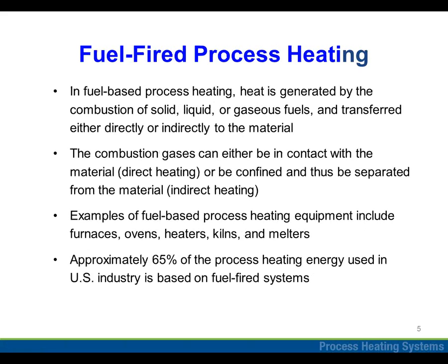So let's take a look at the fuel-fired heating system. In this case, the heat is generated by using solid, liquid, or gaseous fuel. We in the United States are very fortunate that we don't have to use solid fuels like coal or wood and liquid fuels like fuel oil, because we have plenty of clean natural gas, and most processes that you have, I guess almost all other than the electric arc furnace, use natural gas. And then once you burn it, it gives up the heat and you transfer the heat to the material.